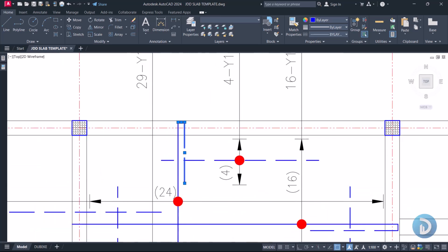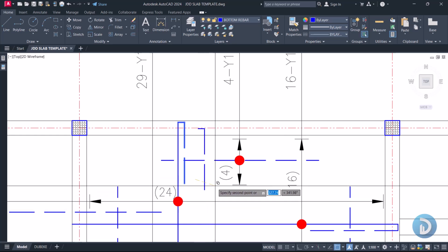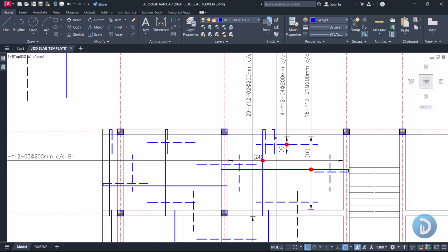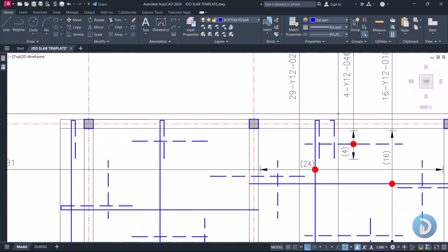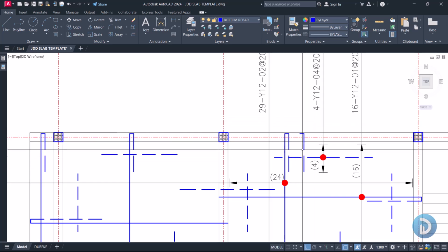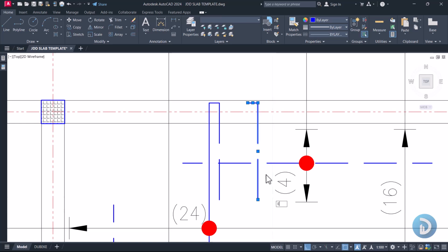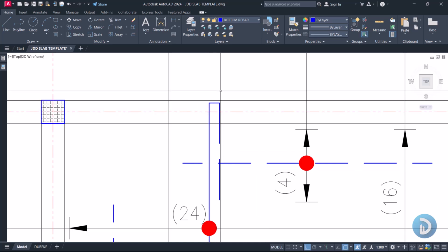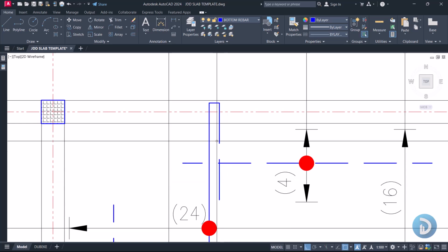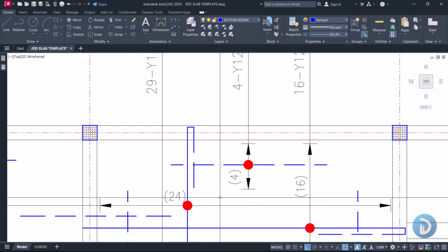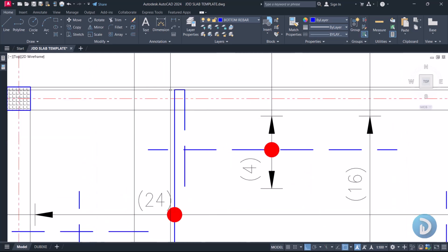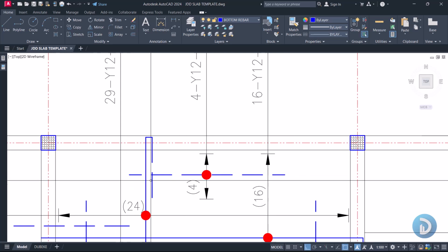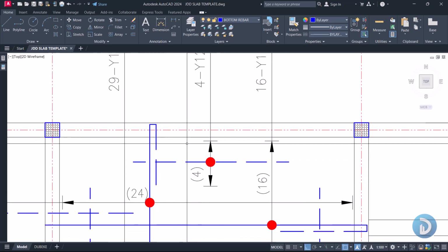Now if we had called out this reinforcement separately, like we said earlier, then we can now detail this other top bar up to this part, and this will now serve as our T1. But for us not to have so many lines on this drawing, since when they are constructing on site, they just have to return this reinforcement to this other panel, we don't necessarily need to differentiate them. By this indication, they will understand that when they return this reinforcement at the top zone, this will be used to redistribute this load across this top zone from here to this point.